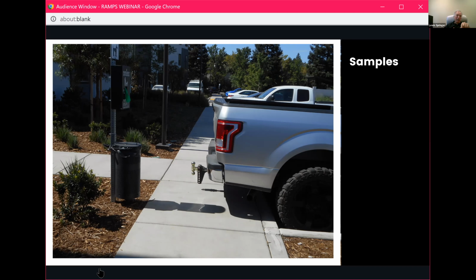But it brings up an interesting concept of why, if you go and drive around, and actually when I did the survey on this, all the accessible parking spaces had wheel stops, because it was built under the 2016 code, so that vehicles in the accessible spaces couldn't drive over and block the accessible route. But every other parking space in the entire development didn't have wheel stops, so everyone can drive over and block the accessible route. Okay.